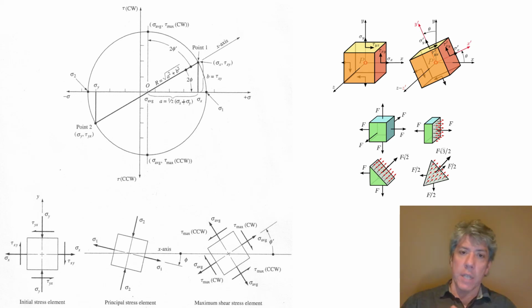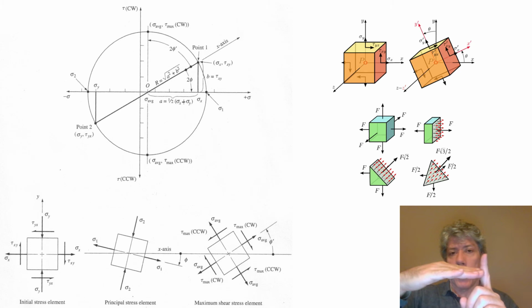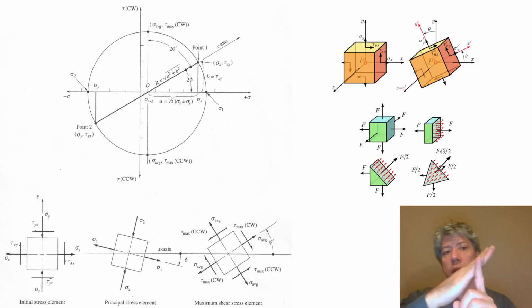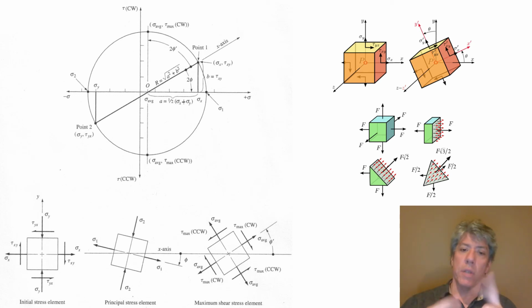And the reason for that is because from Mohr's circle, that horizontal plane cutting the dog bone that way is arbitrary, right? Rather, cut it at an angle where you see the largest shear stress. That's the plane along which failure is going to occur, because the shear stress is going to be too large for the material to take, and the largest direction of that shear stress is along that inclined plane, and so that's the way it's going to fail.